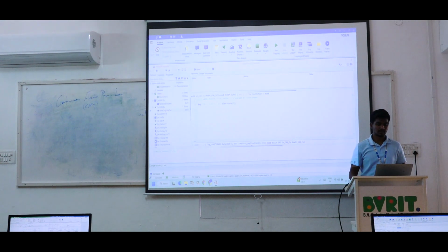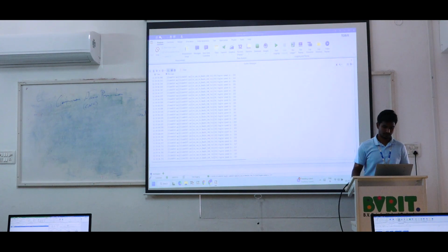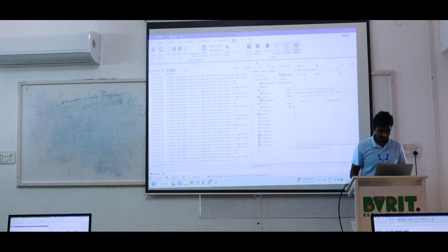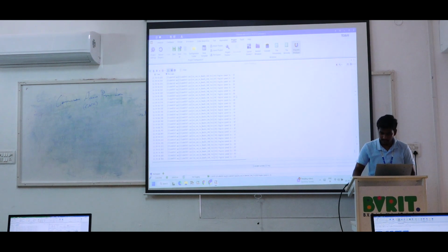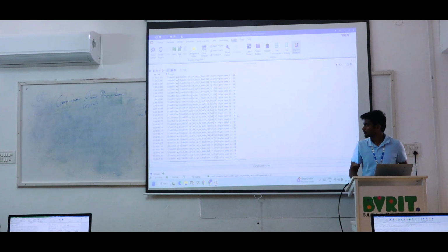After starting, please parallelly check whether CAPL scripting is running or not. If it is not running, please turn on the script. Afterwards, go to messages. Okay. Here you can see the engine speed value is showing. Got it?